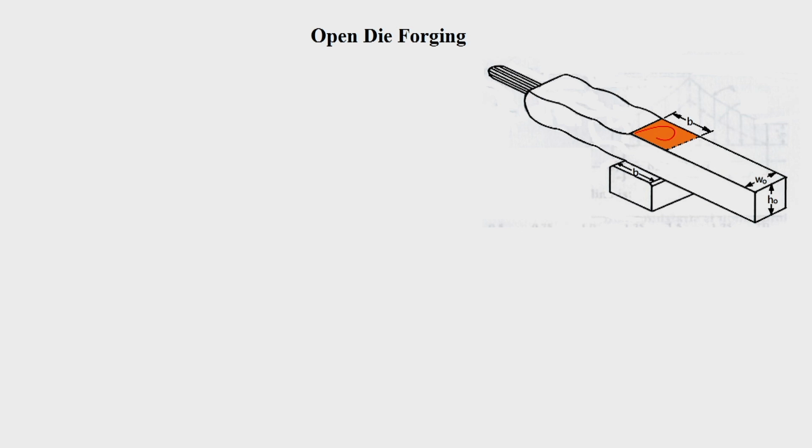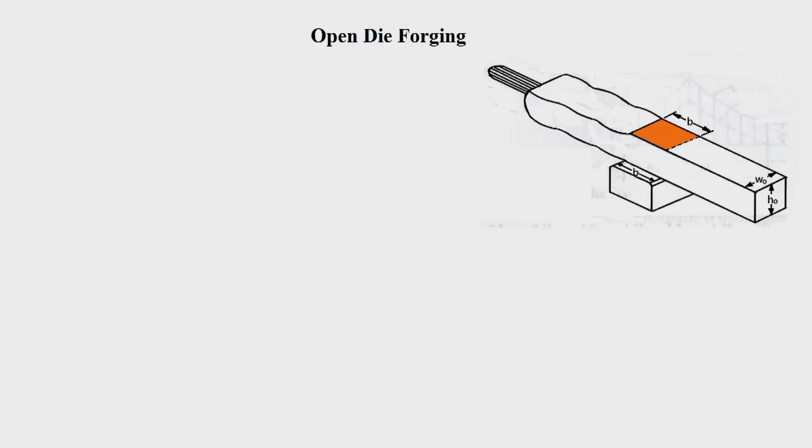When you are doing this, the billet size is much larger than your tools. At any time, the deformation is confined to a small area like this, not along the full length of your ingot. At every stage it deforms by a small amount. There is a change in the cross section area, you may rotate it by 90 degrees. The moment it is pressing, normally the lateral flow of the material will be there, and when you rotate it by another 90 degrees, again that height gets reduced.